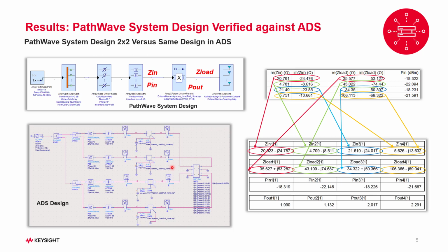We always consider circuit simulators like Advanced Design System as golden standard because they start with the device models and they have very powerful techniques like transient spice or harmonic balance techniques to predict the complex voltages and currents in a network. As we can see in the ADS design, we connected the electronics, including the load pulled X parameter model, to the S parameter matrix of the antenna array. After simulation, we can predict the impedances experienced by the amplifiers looking into the S matrix. On the right-hand side, we can see that our prediction from circuit simulator and system level simulator agree pretty accurately.